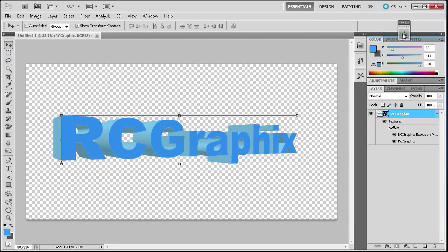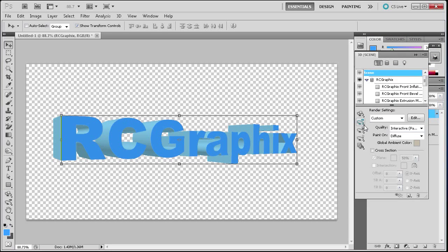The larger the text you have, the longer it's going to take to do this, and it's probably going to take a while regardless. So I'm just going to start it, and then I'm going to speed up the footage so you can see what it's doing. So let's do it. We're going to go to Quality and then go down to Ray Traced Final.